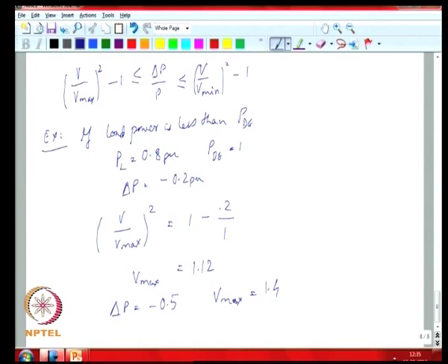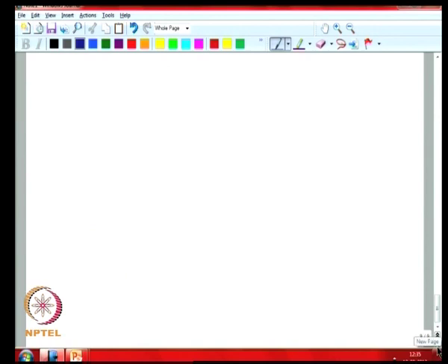Okay. So, you could also look at the other situation where your DG power is much less than the load power. That might be more common, where your DG might be a few solar panels and your feeder might be having a much larger total loading.